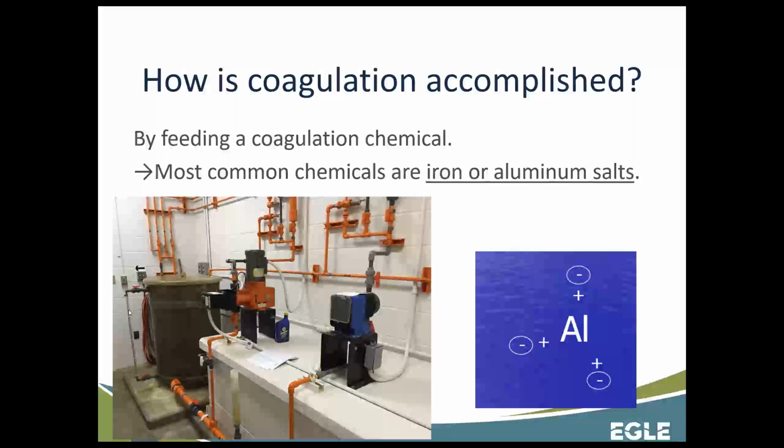Does it look like we've fed about the right amount of coagulant since last time I made my rounds? And you can take a look at the site tube and know. Yes, I'm 2 hours into the shift and I've used about a quarter of what I'd expect. Or, on the flip side, I was in here an hour ago and there was the same amount of coagulant in the tank. Well, that's a red flag, probably an issue.